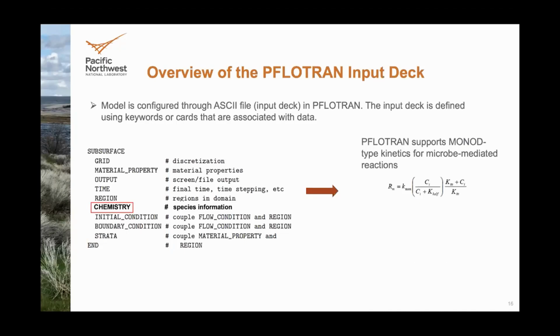Flotran also supports Monod-type kinetics for microbially mediated reactions. This is the Monod-type reaction kinetics shown below. We can add as many Monod terms as we want, and we can also add the inhibition terms at the end.